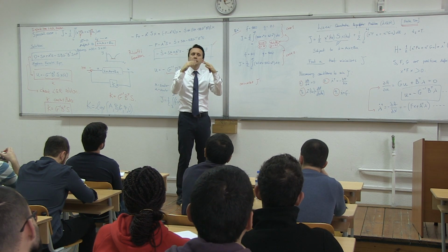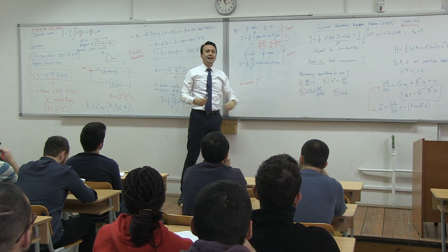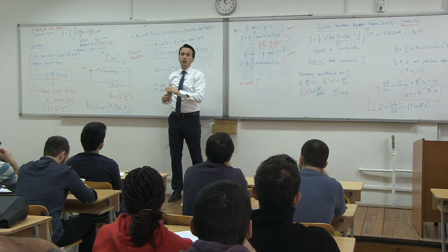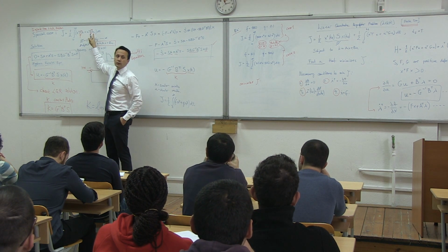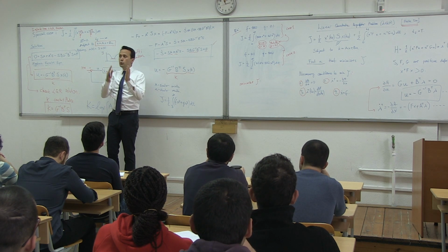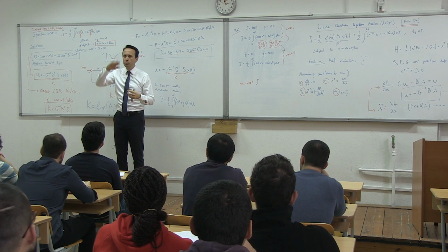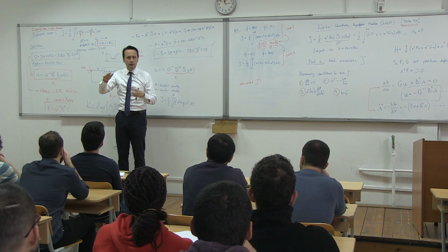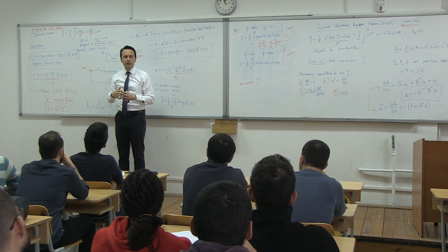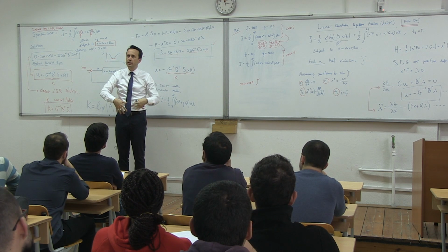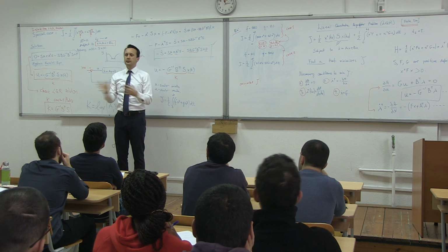All right? But here's the goal. We as controls engineers, we can choose f and g and can tell the problem which one is more important to us. Remember, x is the state, u is the control. Okay? So which one of those do you want to put importance on? What is more important? u is the input to the system. u is the aileron, the elevator, the throttle, right? That's u. And x is the state. Angular velocities, angles, velocities, and all that. Which one is more important for you so that it doesn't move too much?